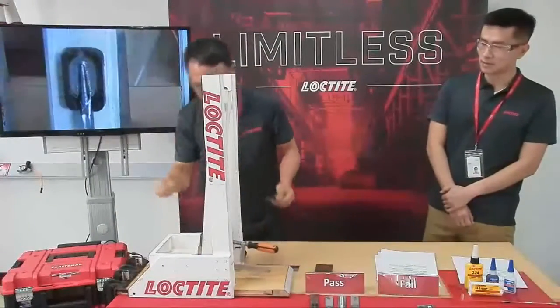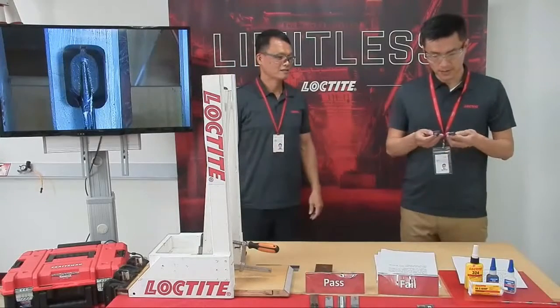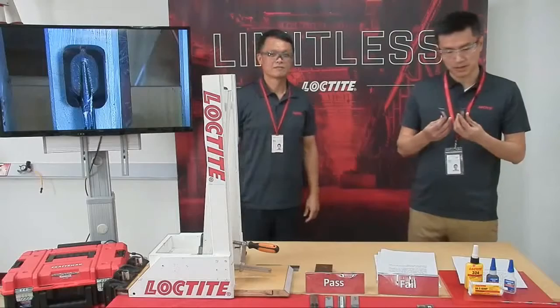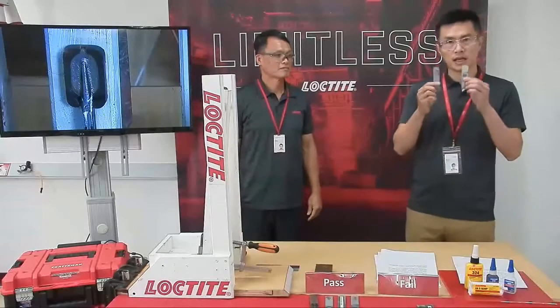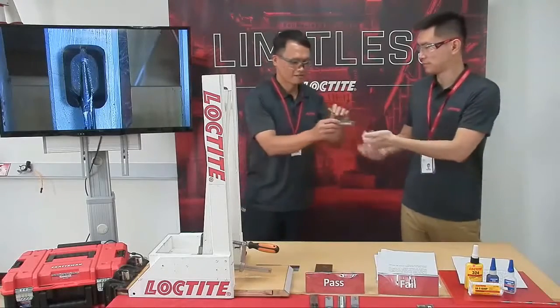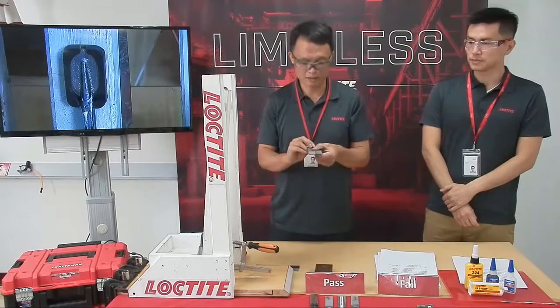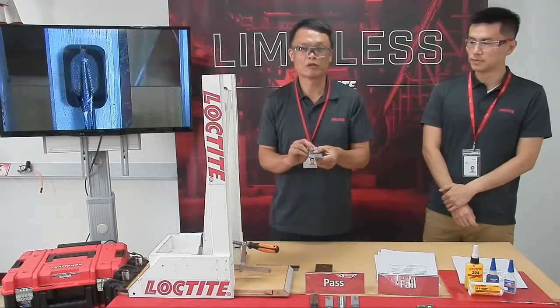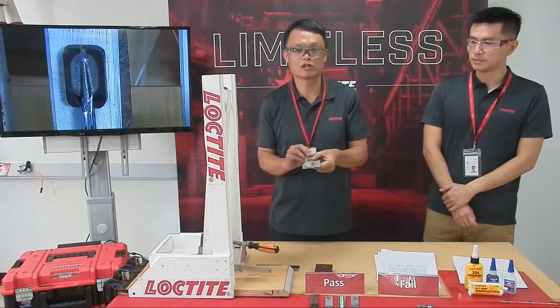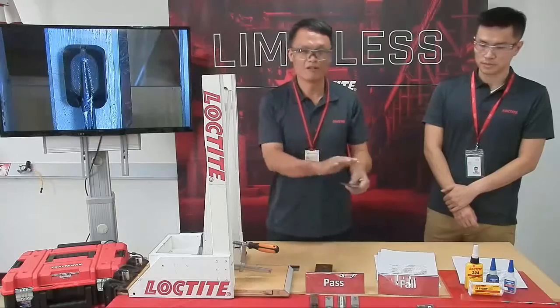Wow. Well, I believe this one has to be out of this game. Yeah, I thought the welding should be strong enough, but actually it broke. It separated completely. Later on, we can have a very close look at the failed specimen. All the joints break from the welding place. That means there is a very serious stress concentration on the welding joint, which most structural engineers do not want to see. But let's move it to the failed area.